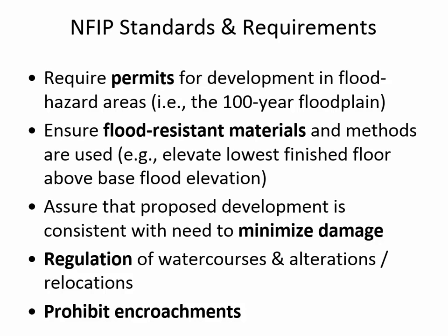The floodplain manager is supposed to make sure that homes that are at risk are using flood-resistant materials, and so that can be building materials that, if they get wet, dry out more easily. It can be vented basements. There are some structures that are built specifically so that when the floodwaters come up, the water can move in and move out of the structure without breaking apart the blocks, basically putting someplace into the structure that the water is designed to flow through, rather than scouring or damaging the foundation of the building.